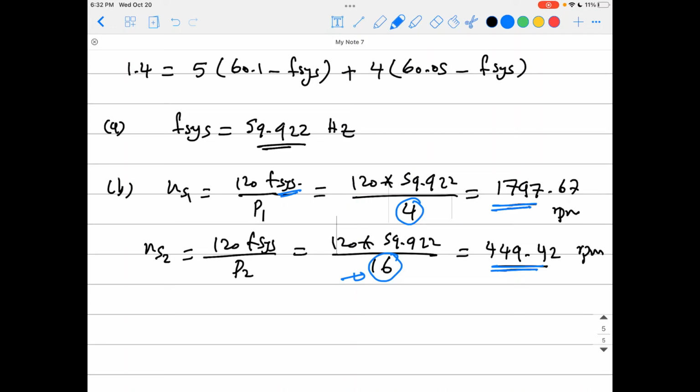And that's why, if you remember when we talked about the difference between the cylindrical and the salient pole rotors of this generator, we said that the salient pole rotor is used for low speed applications because it's not as mechanically rigid as the cylindrical one. So most of the time, the salient pole rotors of the synchronous generator have a much higher number of poles. Why? Because they typically work at lower speeds, so you need a high number of poles to achieve the same frequency.